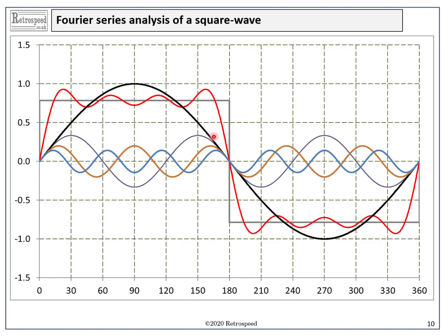Now, the method of resolving the rectangular MMF wave into harmonics is Fourier's series. And I should mention here the vital importance of using Fourier's series and not the FFT. The waveforms are periodic, and although there are special cases where the discrete Fourier transform can be identified with some of the coefficients, the FFT is the wrong tool for this work, and we should always use the Fourier series. Otherwise, we'll run the risk of departing from the classical theory and coming up with the wrong winding factors.